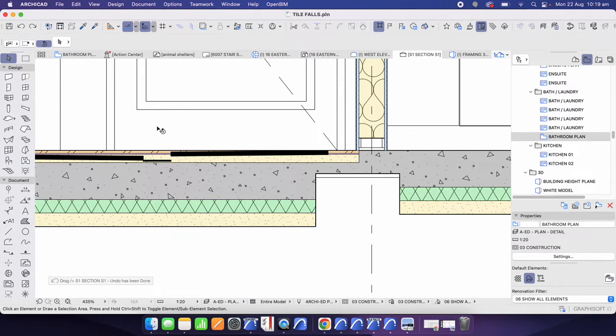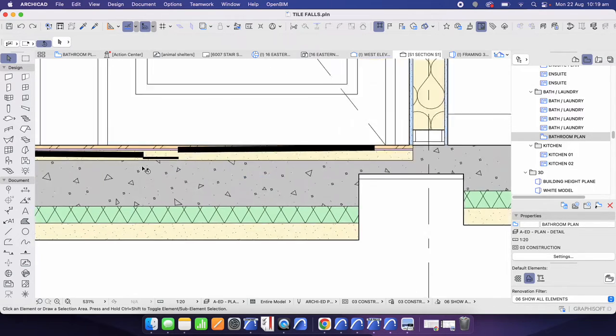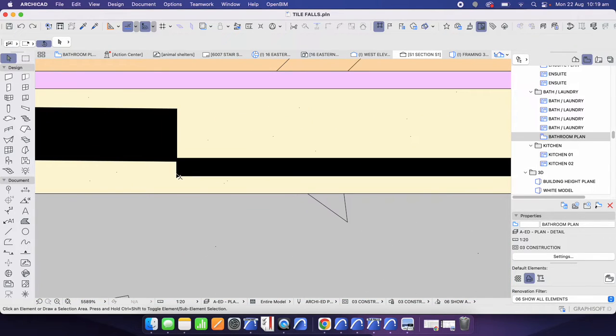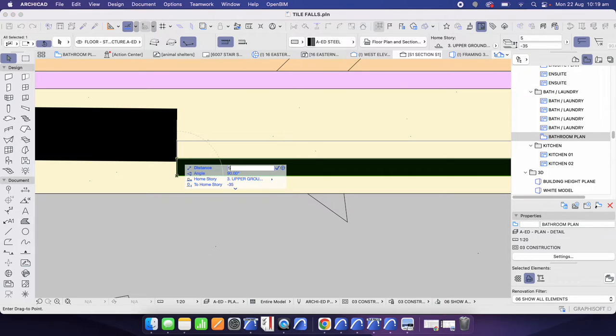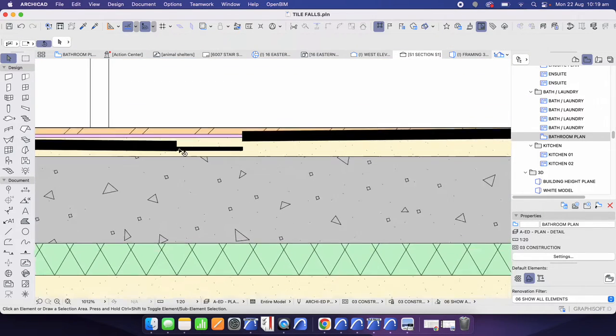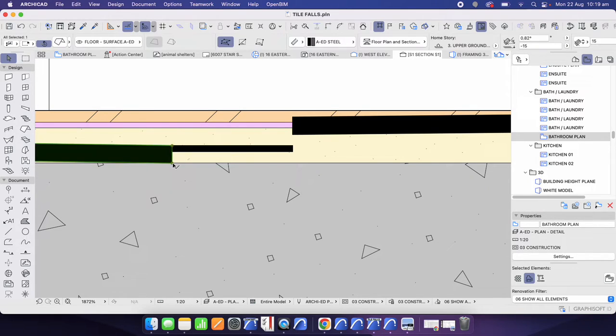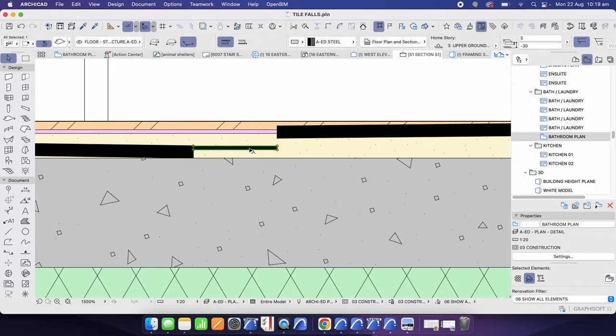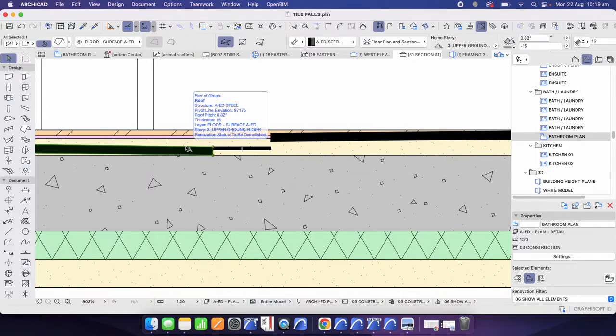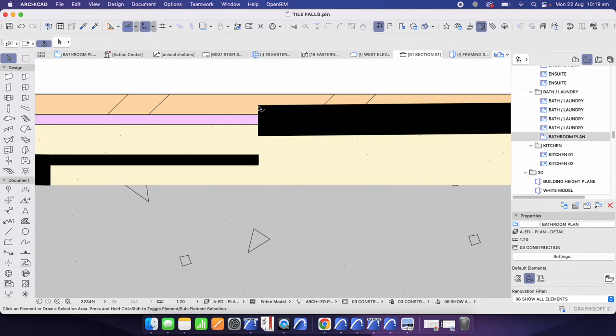In this case, I want to have a nice relationship when I walk in the door from the concrete, which is exposed, to the tile. So I want that corner to be flush. So what I'm going to do is deliberately lower it down. Now again, I've probably made this a little bit low, so I'll bring this up another 5 millimeters, because effectively what needs to happen is I want to be able to bring this down, and I need the glue and the tile to both fit inside. So of course, the point is that the height of this drain is really determined by the tile and the glue, or the tile adhesive that it is fixed to.